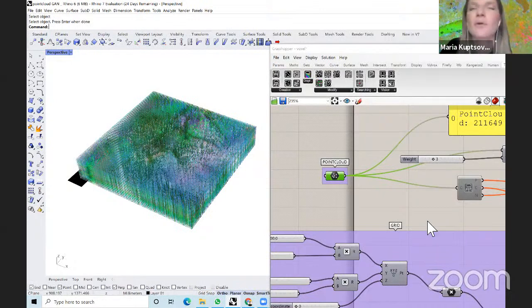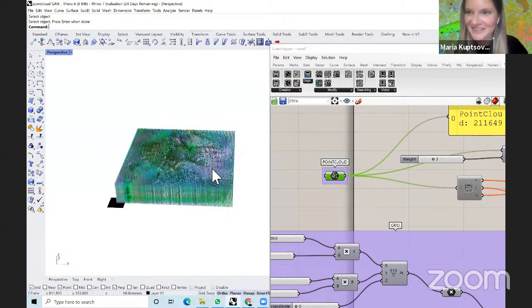we changed the size of your point cloud, and were you selecting for the point cloud generation every fifth point or every point? What is the size of the point cloud itself? If you can tell me these variables, I can tell you if it will handle it or not. Because Rhino is only using a quarter of the computer, there are some limits in processing heavy point clouds. That's why at a certain moment we introduce Python or coding directly, because it's easier and lighter to calculate the code rather than the visual stuff